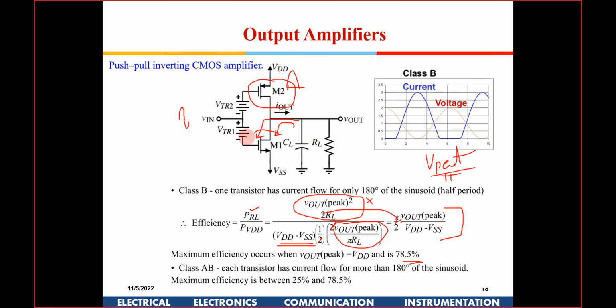But you are giving the threshold voltages also. In an inverter we have that small region in between, like initially till it comes to VTN, this will not be switched on. But we are ensuring that even for a small positive voltage, this will be switched on by biasing it. Similarly, for a small negative voltage, the top one will also be switched on.